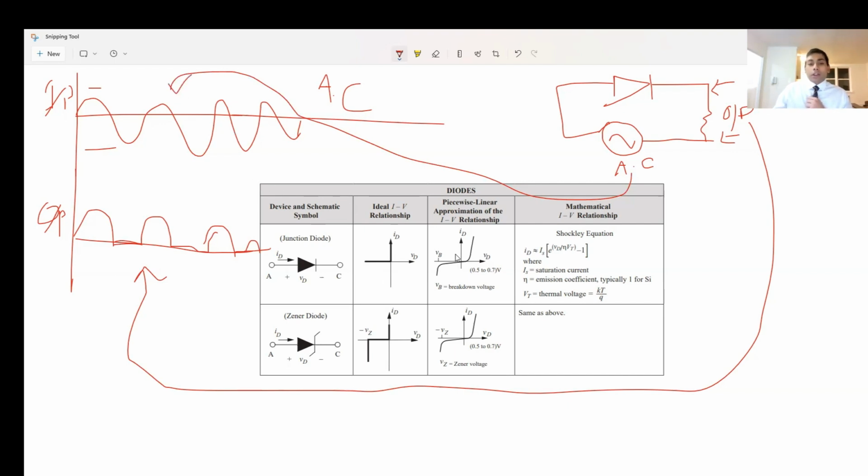Okay. So if you're trying to measure how much current, now you can see in this case, it's a series circuit, right? Because it's just connected across in one node. If you're trying to measure exactly how much current is flowing through this diode, or in this circuit, because it's a series circuit, a graph would usually look like this, where you can see that it does not conduct until you apply at least a minimum voltage of 0.5 to 0.7.